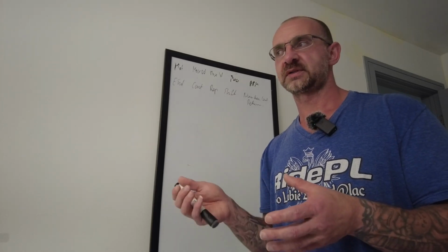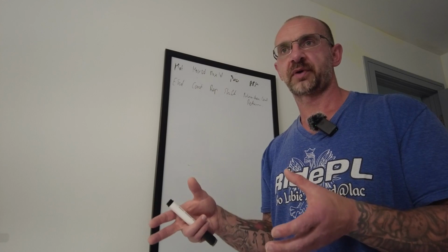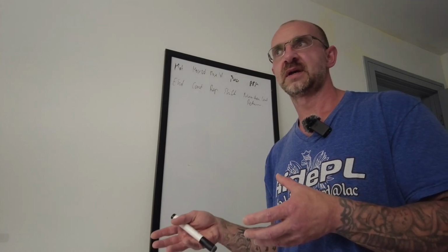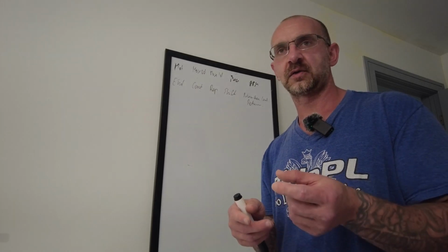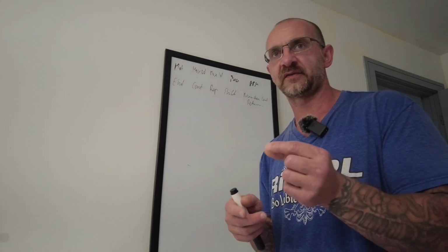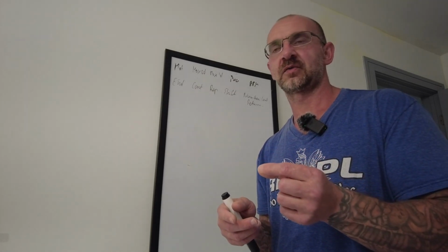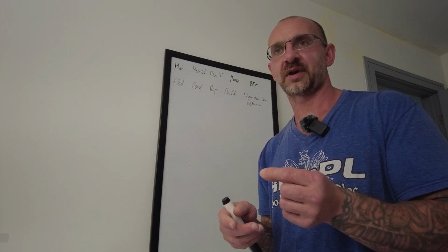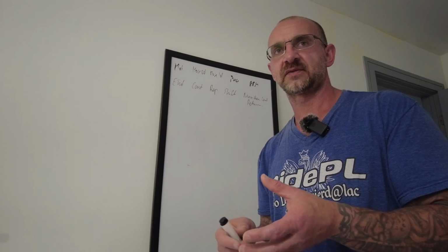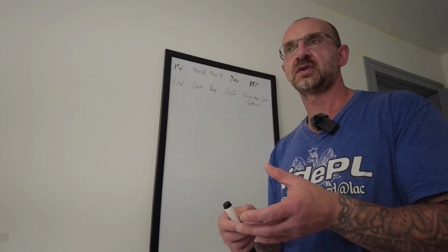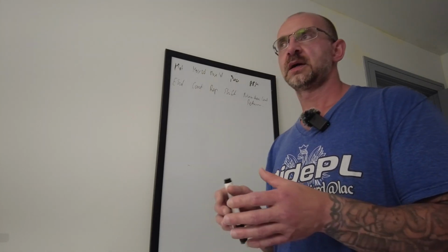Which might work, but sometimes we make small parts, big parts, long parts. It depends on your holding. Sometimes you have a lot of holding, sometimes you're holding by very little. Obviously, you're not gonna go with crazy cuts because pretty much your part's gonna fly out of your holding. It doesn't matter if you hold in a chuck or using a collet system.